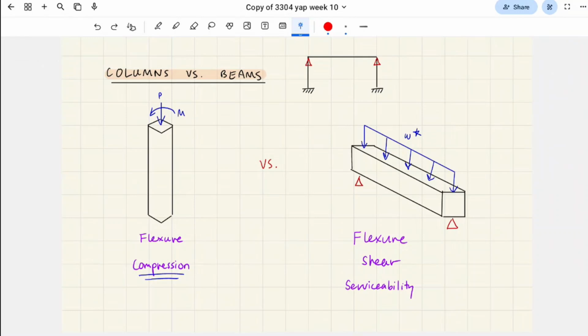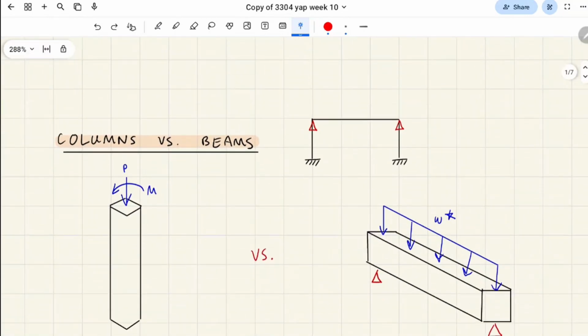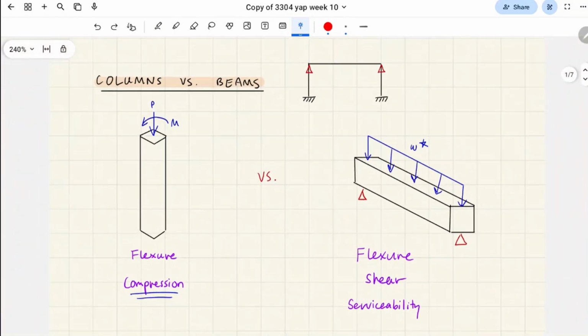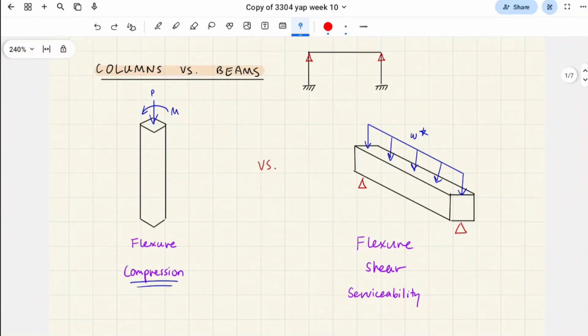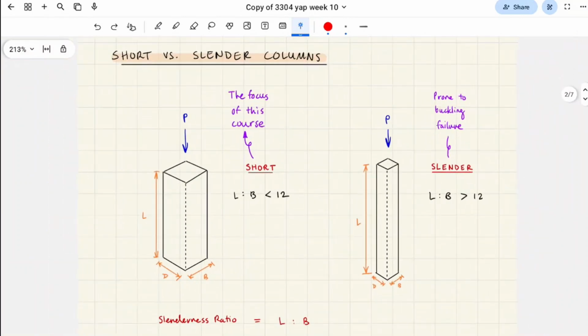So we consider axial forces. We consider compression. So P is compression and M is the moments. That's from the semi-rigid connection. Sometimes you have a bending moment applied on the beam, and compression comes from those dead loads and live loads, or gravity loads, I guess. But yeah, hopefully that makes sense. I feel like that one's not too bad to understand.